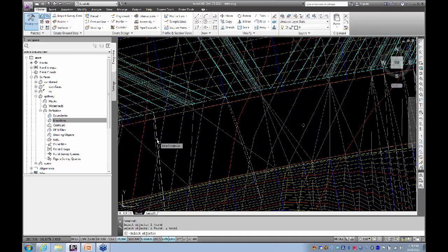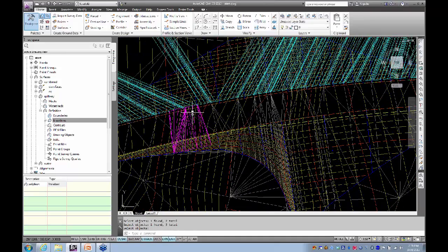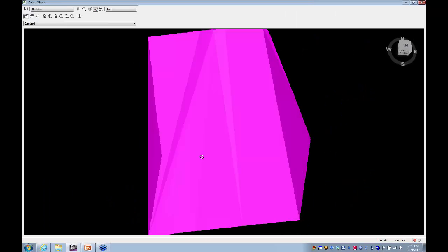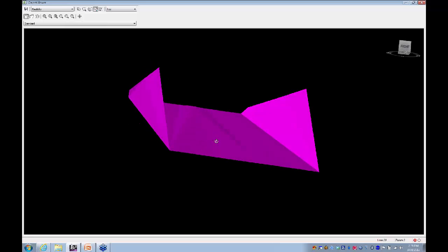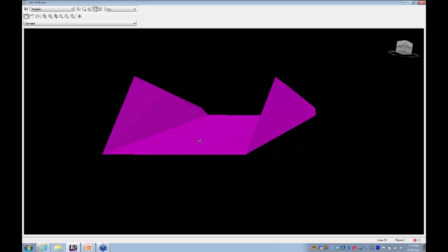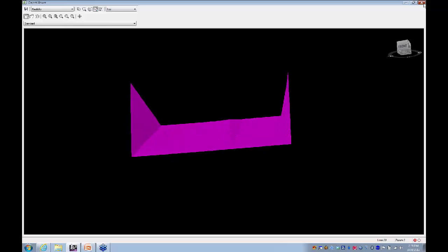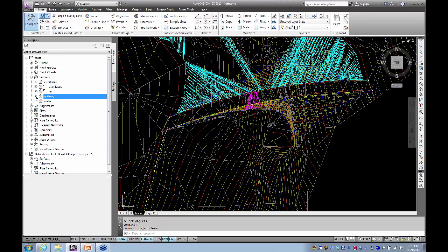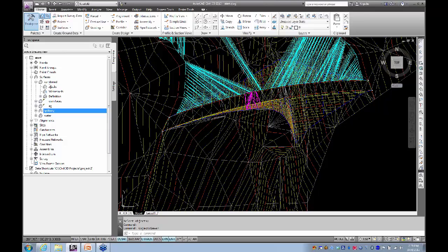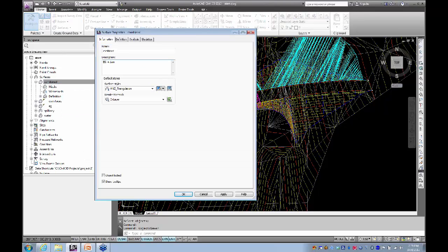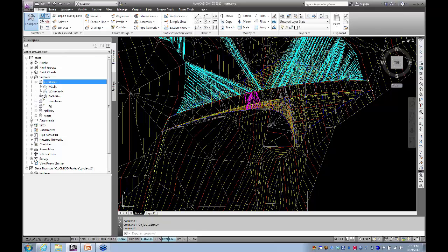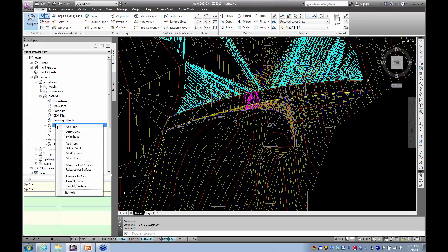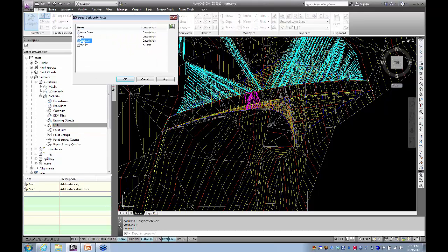Select that one, and that one, hit enter. And again, check it out to make sure you got it right. That's not too bad as a surface. Okay, and simply now add that into our combined surface. So again, find our combined surface here. Probably want to go into the surface properties, into definition, EG plus dam plus spillway. Make it easy for those following on. Go OK. And then just simply expand out the definition under the edits, paste in a new surface called spillway.